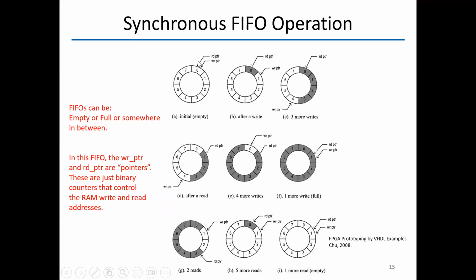We spoke last time, we said that this is the read pointer and the write pointer, and everything is free. If I write one slot, my pointer will move, pointing to the coming empty slot. If I write three more, 1, 2, 3, I'm going to be pointing at slot 5, that is number 4. And if I start reading, I am clearing whatever was in here for coming writes.